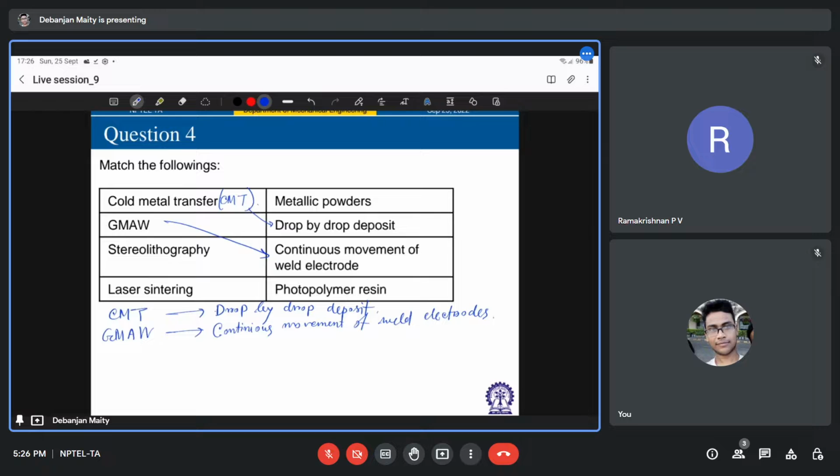And again the wire moves forward to create another arc, right? So all these phenomena happen several times in each second. So basically, cold metal transfer provides a controlled method of material deposition by a sophisticated wire feed system at low thermal input, right?